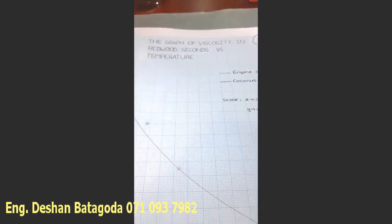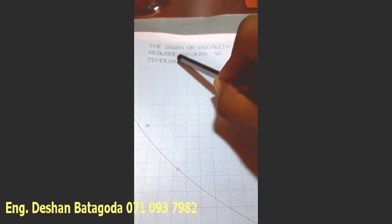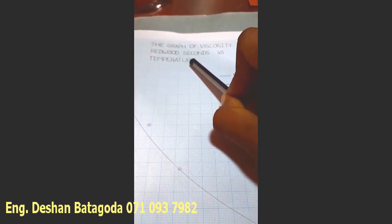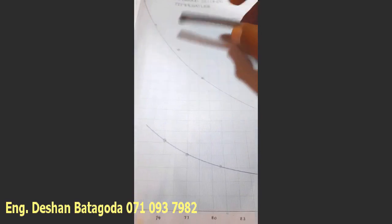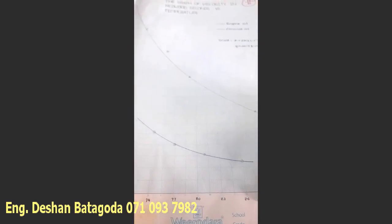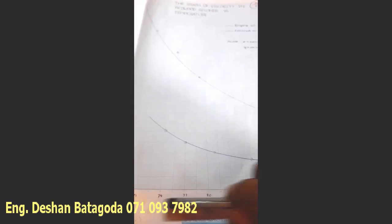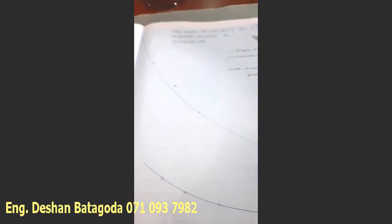So now we have to plot a graph. We have to plot the variation of viscosity in Redwood seconds versus the respective temperature. So here we are going to consider temperature on the x-axis. The respective temperature values we are going to place on the x-axis. Then with respect to that, we are going to mark the respective viscosity values that you have calculated in Redwood seconds on the y-axis.